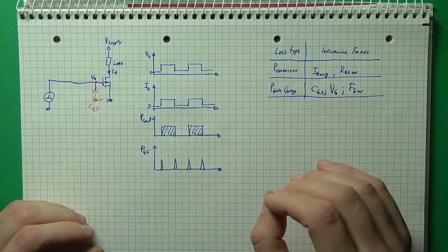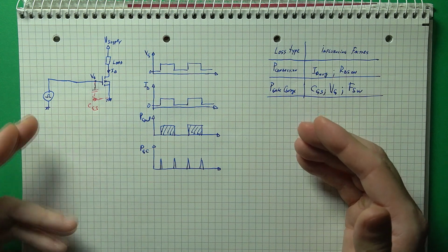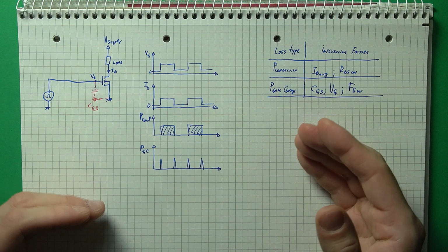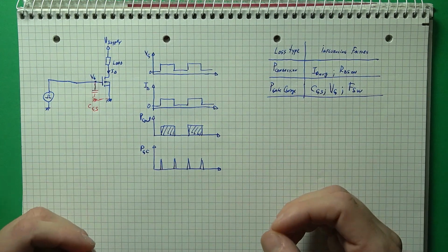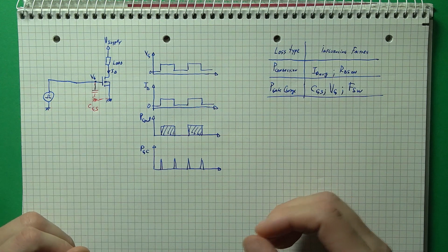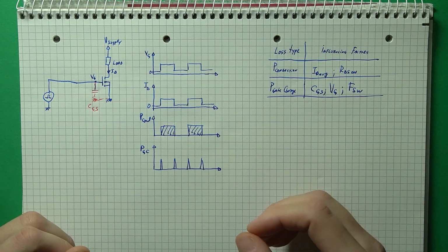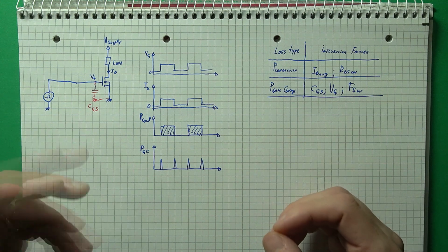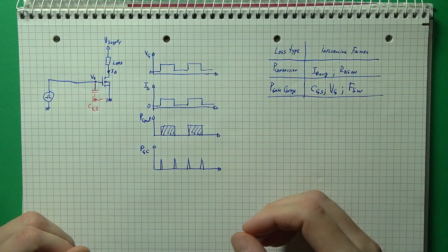Now, even though this loss is not occurring on the transistor itself, most of it is dissipated on the driver, it can still be a significant quantity of loss. So it's important to consider. The main parameters impacting this type of loss are the gate capacitance, the voltage to which the gate is being charged and then discharged from, and finally the switching frequency, how often is this capacitance being charged and discharged, since this loss is occurring at every switching cycle.